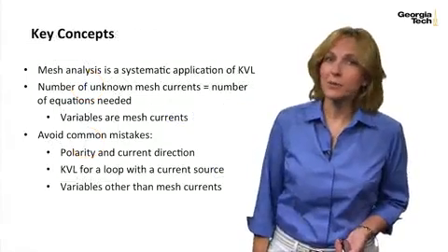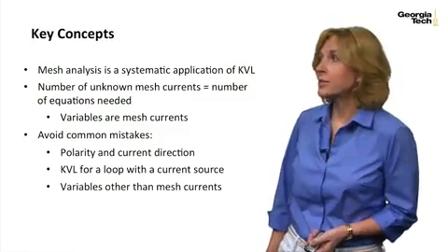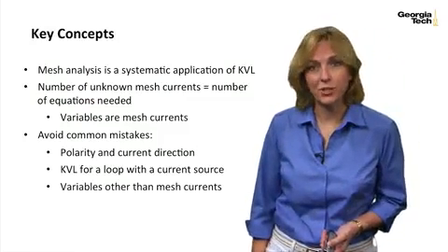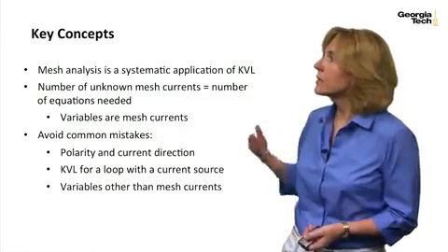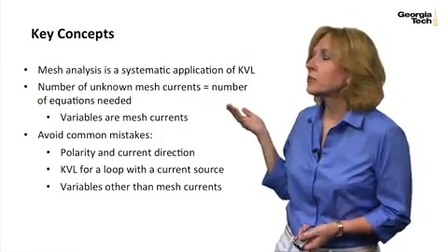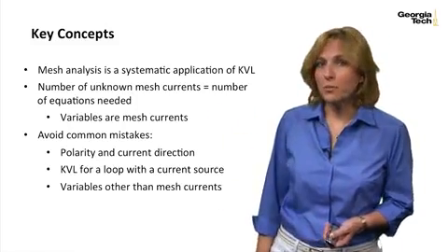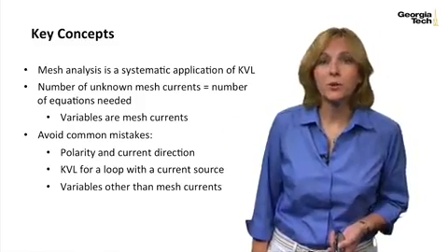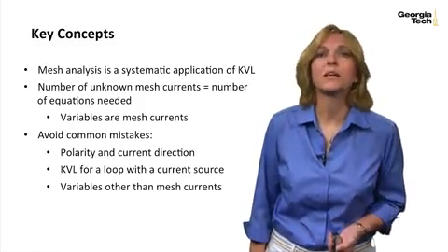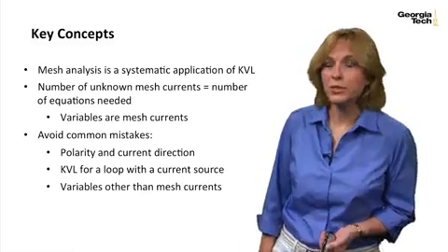The key concepts we've covered in this lesson, first of all, is that mesh analysis is a systematic application of the KVL. The number of mesh currents is equal to the number of equations needed. The variables are mesh currents, so make sure that whenever you write your equations, you ignore any other variables. The only variables should be those mesh currents.